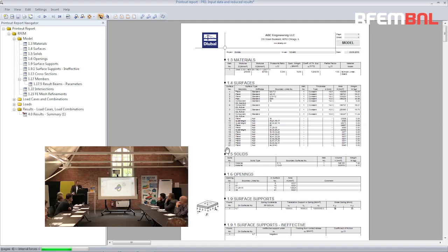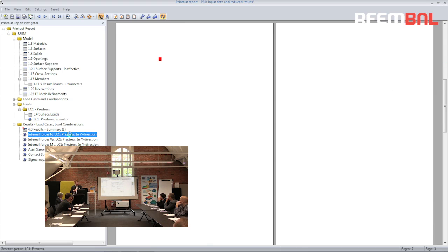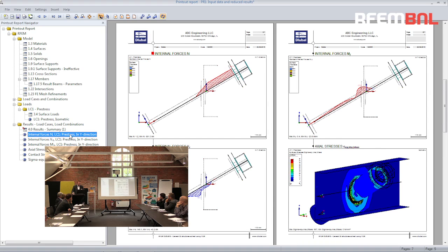And the final one is maybe the solid stress. Yeah? Something like this. And I will use Ctrl P. Printout report current only. I don't want to mass print, but I would like to see the printout report on OK. So now automatically RFEM has stored the pictures at the correct locations if I did it correctly. If not, I can always make slight adjustments on the pictures. It's updating the pictures here, like this.